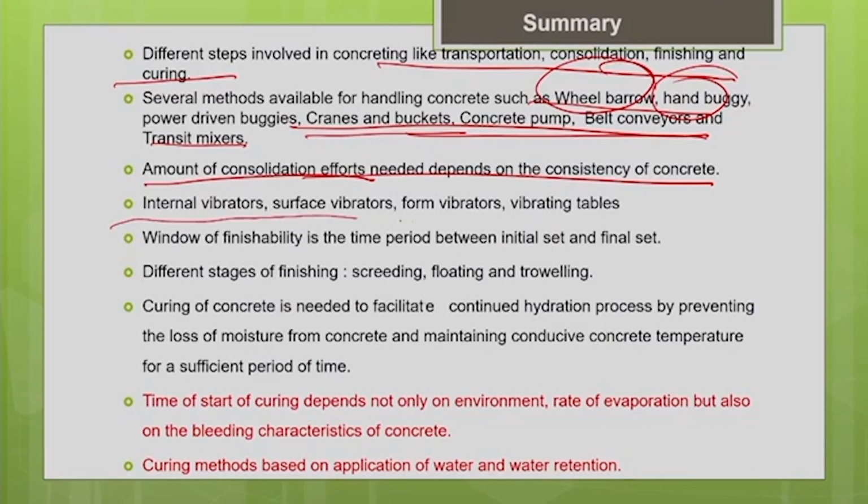Different methods are available, starting from internal vibrators, surface vibrators, form vibrators and vibrating tables. The best are internal vibrators, but in some locations internal vibrators are not feasible, either because of thin sections or because of congested reinforcement. In those cases we have to go for either surface vibrators or external vibrators.